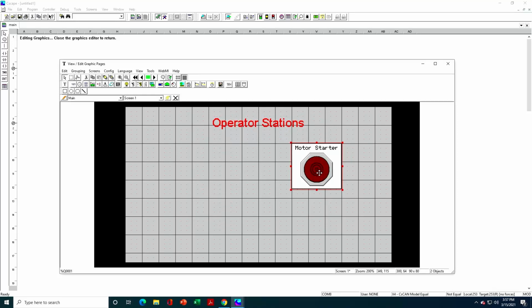Okay, so now we have an indicator that whenever the motor starter is running, it's going to turn bright red. When the motor starter is not running, it's going to stay a dark red. Now, how do I know more or less what it looks like when that happens? Well, I do have a little test button here, or operator simulator I can select. And then when I click, it'll show me what the indicator is going to look like. All right, I'll go back to my pointer. All right, now let's get a little bit interesting here.